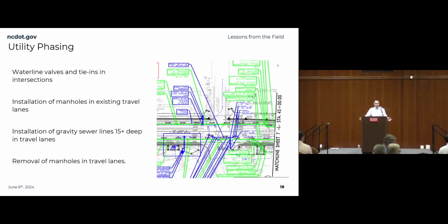And the typical water line depth, they say a minimum cover of 3 feet is reasonable, something we can often do overnight. But sometimes, you can see the green is the proposed sewer and the blue is the proposed water. Now we're working around water and sewer in the same area as well as drainage lines, and your water line depth starts to move, or it's just not a simple tie-in because we're feeding around those other utilities.